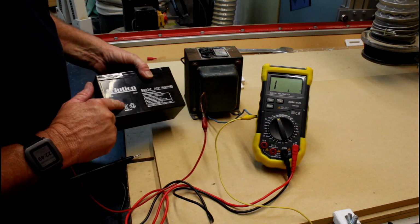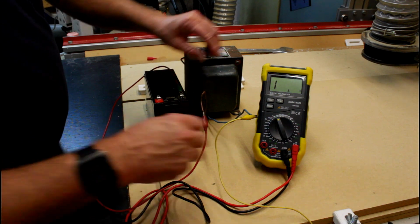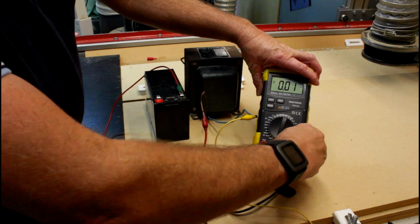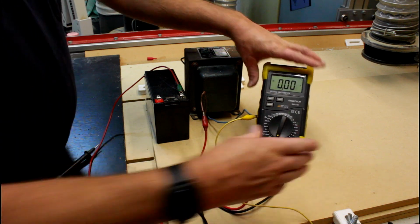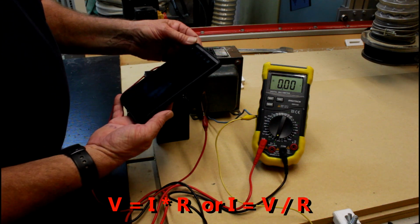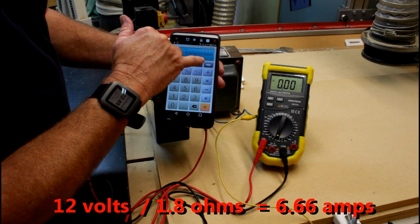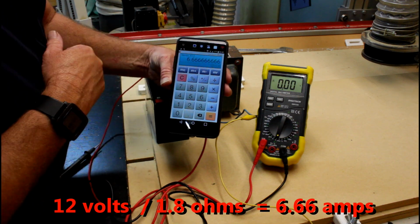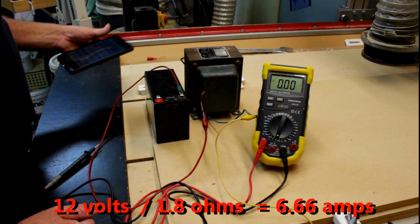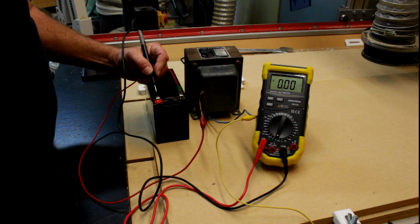I have here a 12 volt battery, so I'm going to put my meter in series with the battery and measure how much current flows through it. So if I take my 12 volts and divide it by my 1.8 ohms, I get a figure of 6.6666 amps of current flowing. So let's just see what happens.